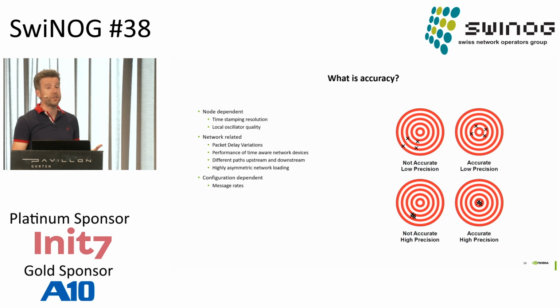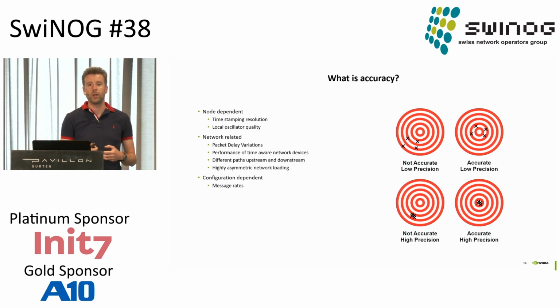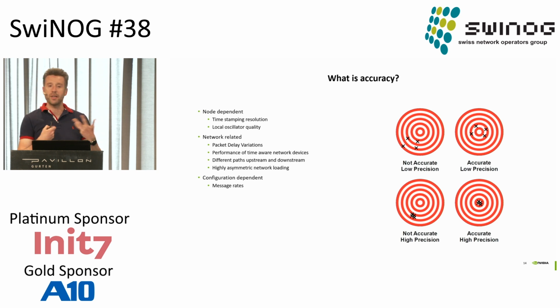So first of all, what is the time-stamping resolution that you're able to use? Do you have a time-stamper that's running at 100 nanoseconds, 10 nanoseconds, 2 nanoseconds? What's the local oscillator quality? And how has it aged? And what's the temperature? And do you have any temperature drift? So all these exist in terms of specification. I'm excluding all the bugs that exist in real-time clocks and implementations on different generations of motherboards and so on and so forth. That's a whole other realm.